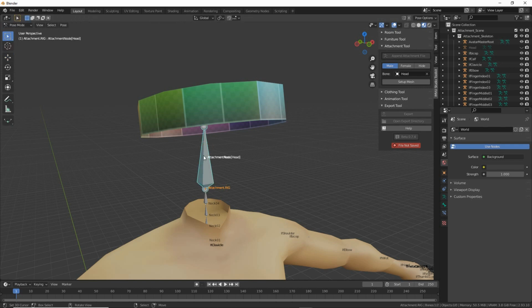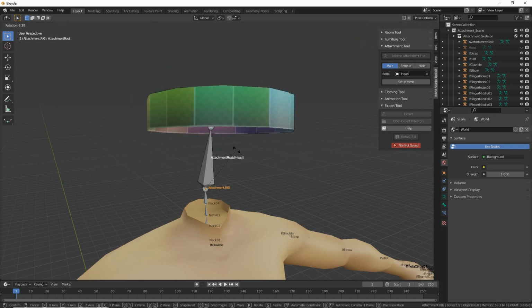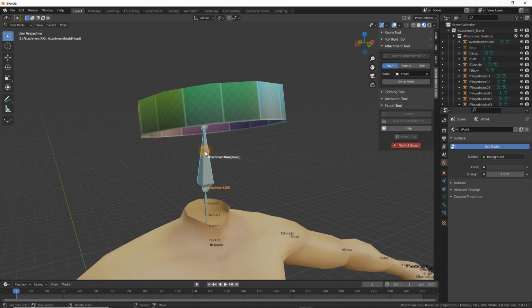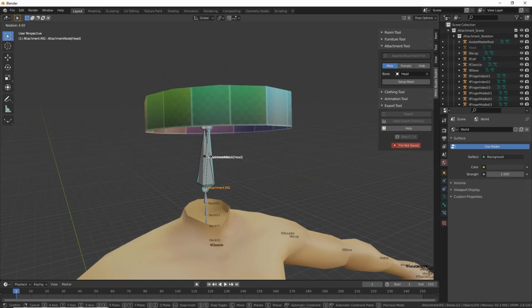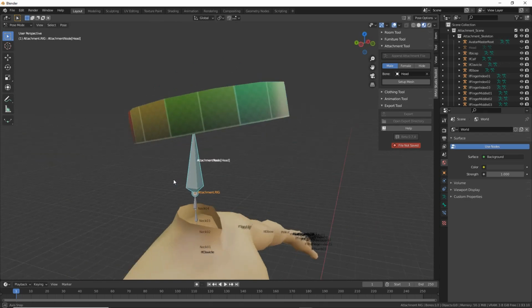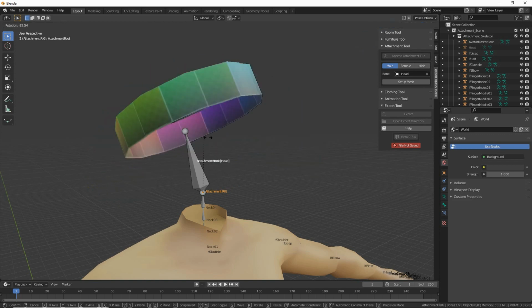And then what we can do is toggle, so click between the two bones that are part of that armature, press the R key, R for rotate, and we can check whether our object moves with the armature. If it does, it means we're set up correctly and we can export. So that test checks out.